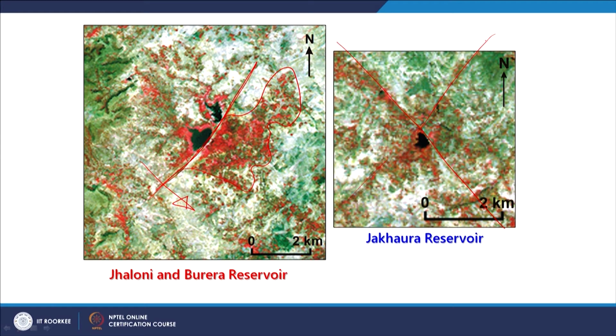So, only along there is maximum movement of water, otherwise in other parts there is no harm. Because remember the early discussion I mentioned, that there is quite sufficient rain precipitation over India. The only thing is we should delay the runoff as much as possible. If we delay it by a few months, it will recharge the groundwater reserve.